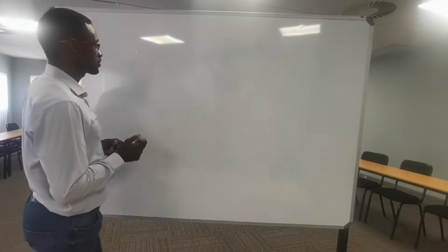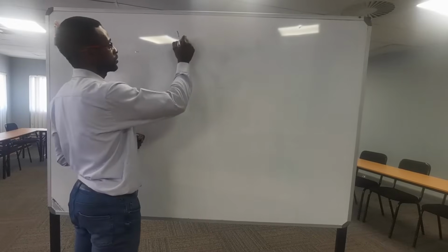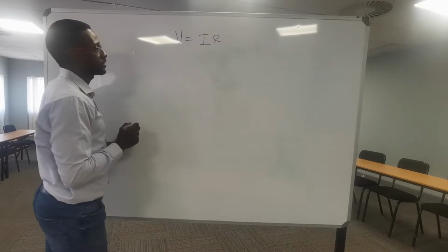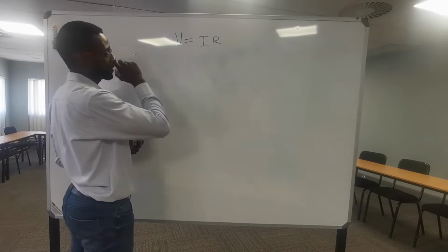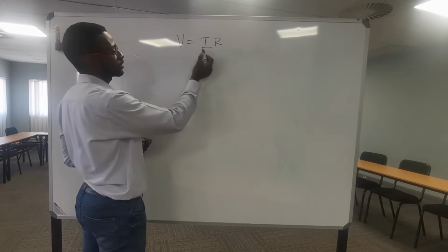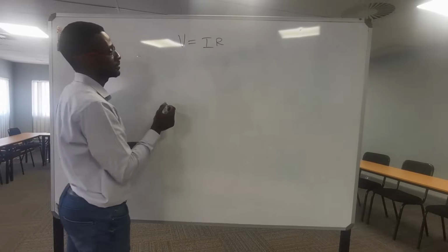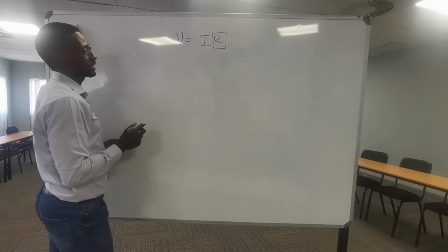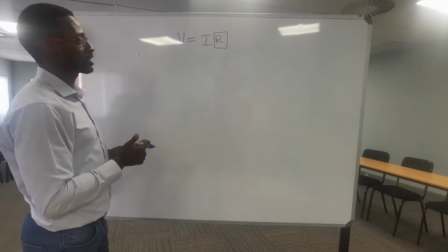The first bit of information I've already covered in the practical discussion that we had, but effectively your practical 2 is a verification of Ohm's law. Ohm's law, what does it state? It should state to you that the voltage across an element is proportional to the current flowing through that element if the load is resistive, right?